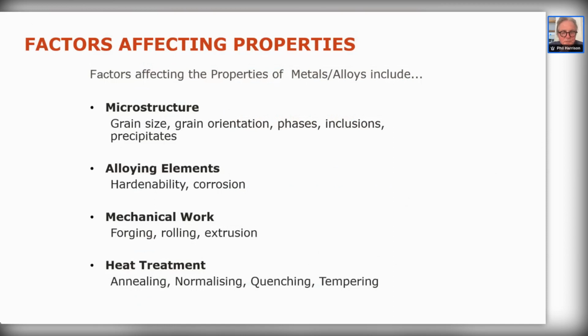And the strange thing is, normalizing and quenching and full annealing of steels are carried out all at the same temperature. The only difference is the cooling rate. Anneal is very, very slow cooled in a furnace. Normalizing is air cooled, and quenching is, as it says, into a quenchant, could be water or oil. When we quench into water or oil with the steel, we form a different phase. The phase is called martensite. It is its own type of phase.